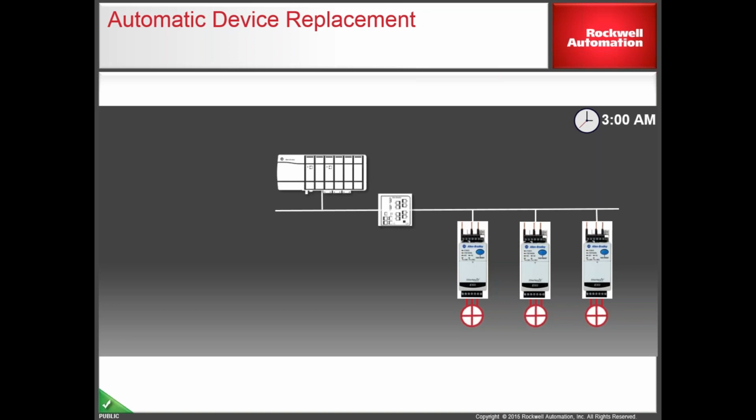If I'm understanding correctly, you were already running online, downloaded to the processor, and then found out that the motor control operating mode wasn't set properly. Yep. In that case, no, you weren't missing anything. You would have to take that offline. I would say inhibit the module, but I think you have to be completely offline to get into the module definition and make those changes.